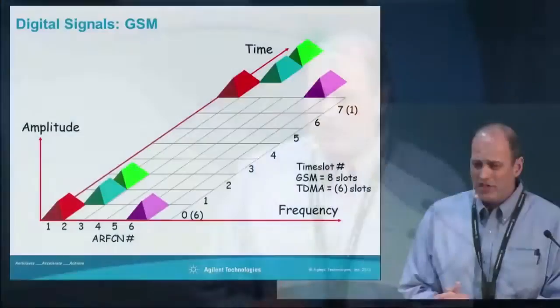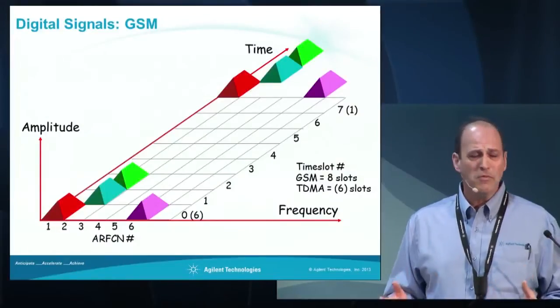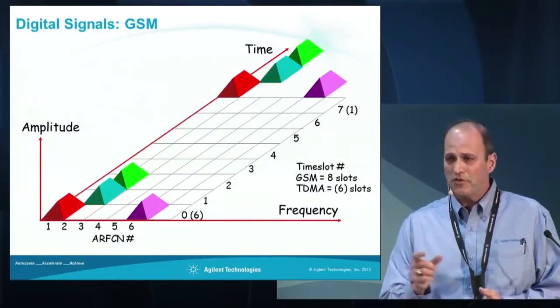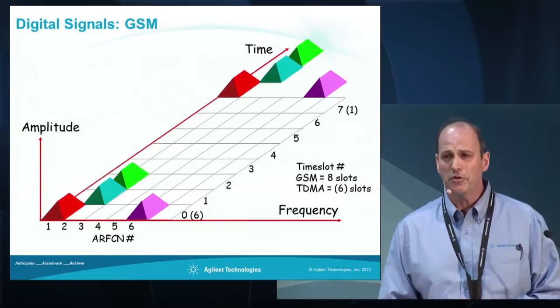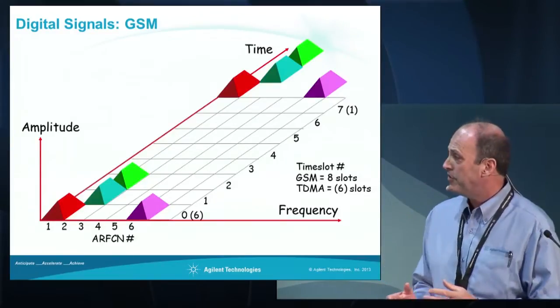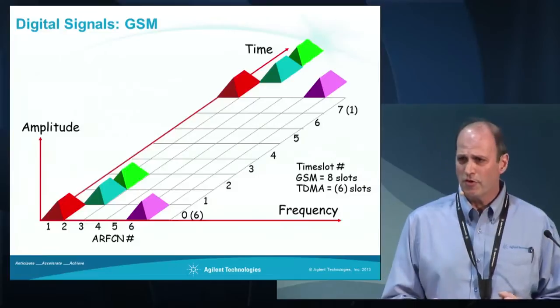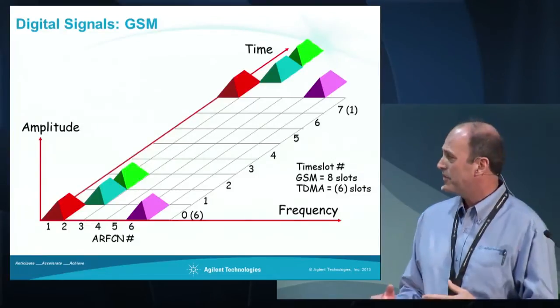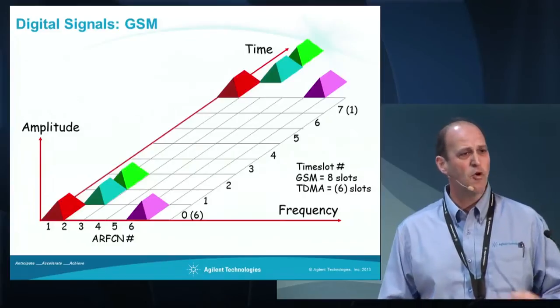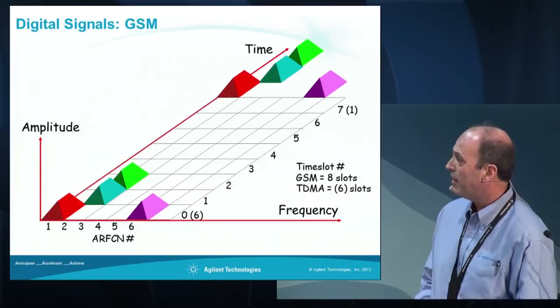So again, using GSM as a real general example, it's a TDMA type system, so there's time slots. So our jamming system might take a couple of different approaches. One might be a little more brute force approach and just block the entire broadcast channel. So that's effective, but that takes more power for a greater period of time.